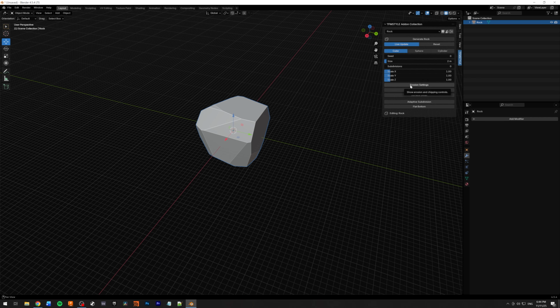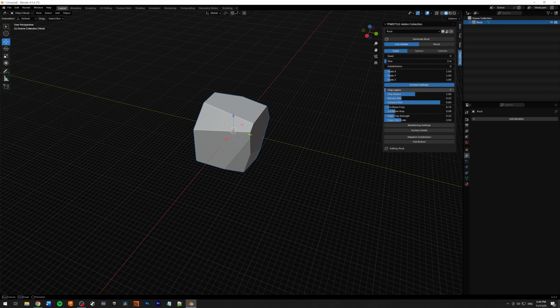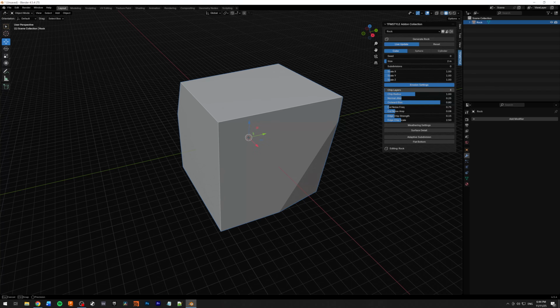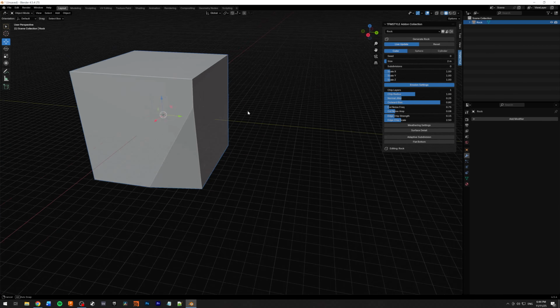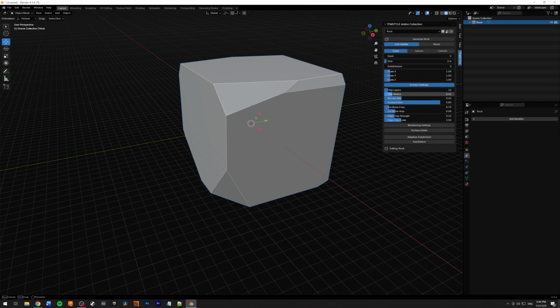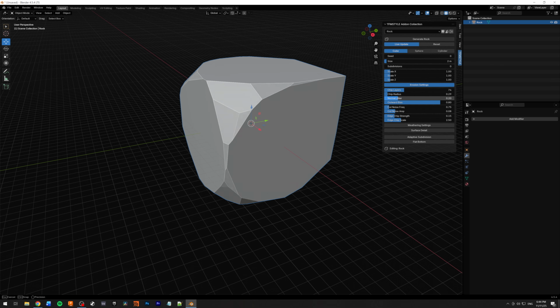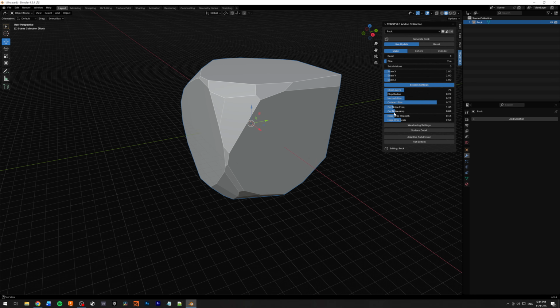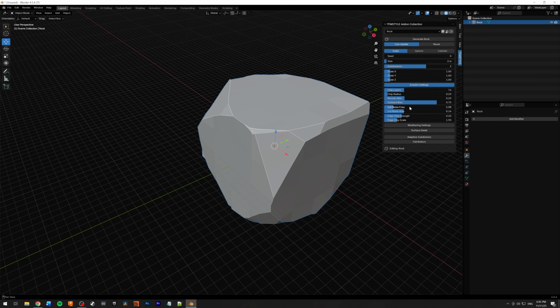So I'm going to go to my erosion setting. And now, as you can see, you can add chips and you can take off part of the stone. So with chip 1, just have one piece missing, and you can increase that. And there's a lot of different options: the chip radius, the jitter, inboard outward bias, some cut noise to add inside of your rock. So of course you will need to add some subdivision to be able to have a little bit more details.